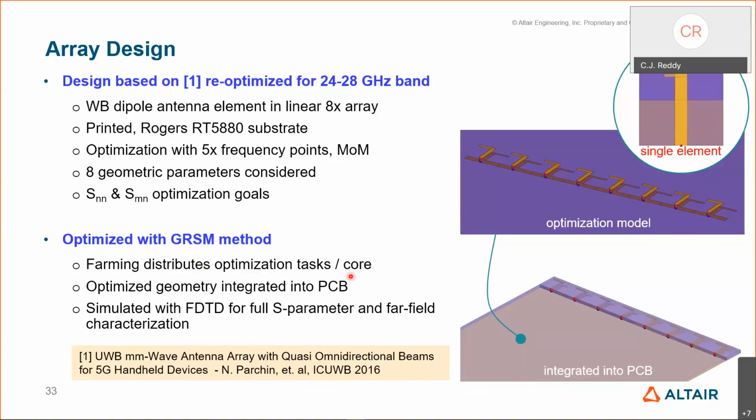And of course, we can form this into various cores. First we optimize this on infinite substrate layers, and then we could optimize that into a PCB with a ground plane, but of course with the dielectric here. And for this we used the FDTD for the simulations.